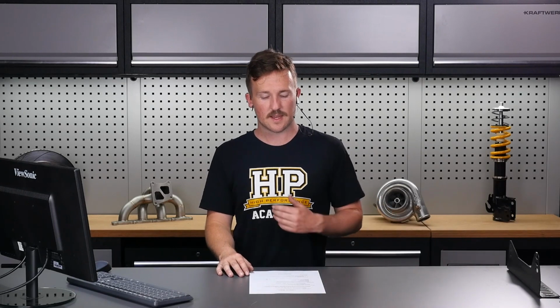But past this, it also allows us to manufacture the part a lot more simply. There's a couple of methods we could use here. Of course, something like CNC laser cutting, or we could simply print it out onto a piece of paper, make a template out of that, and then cut it out of sheet metal ourselves and make the part by normal fabrication methods.